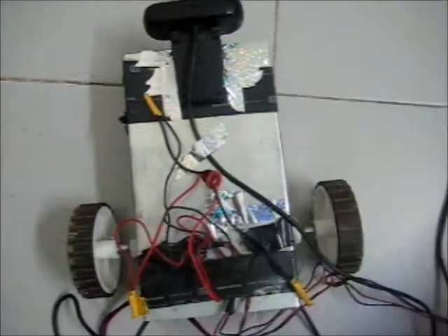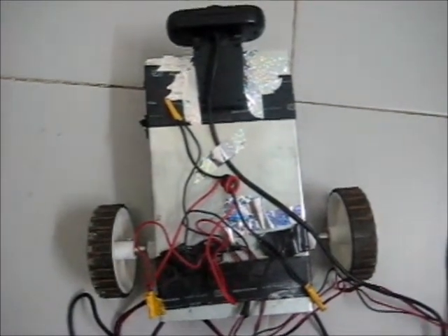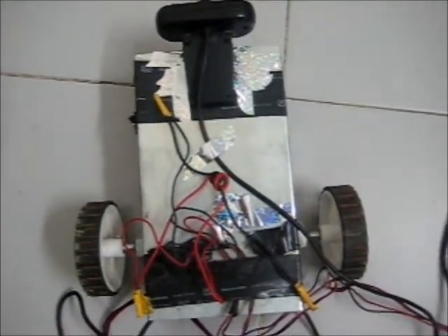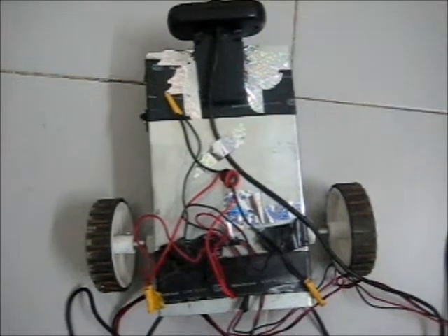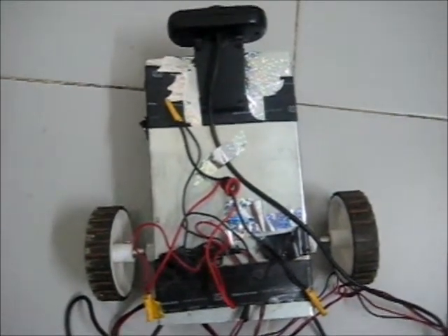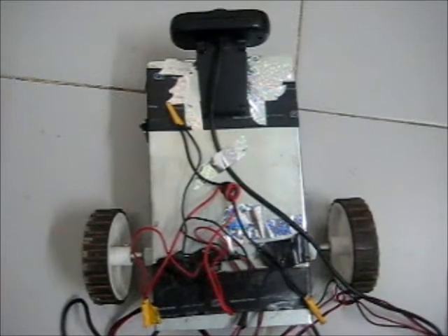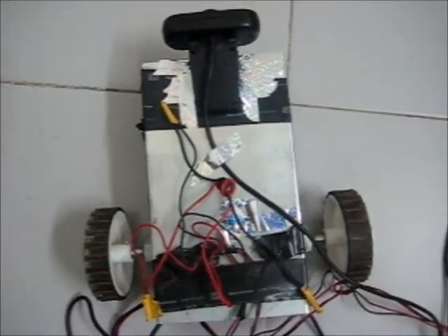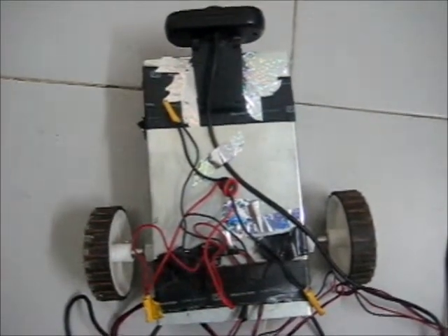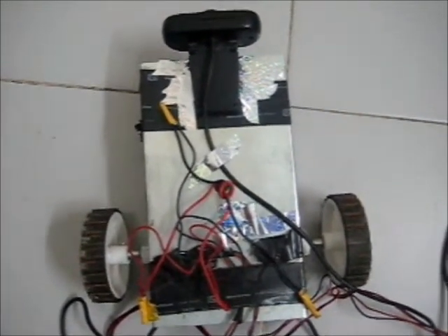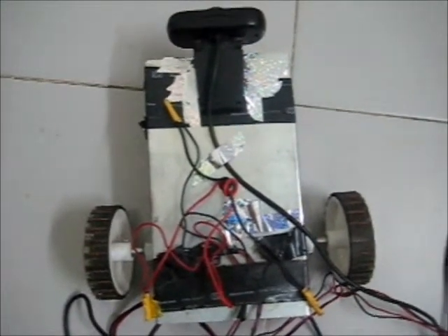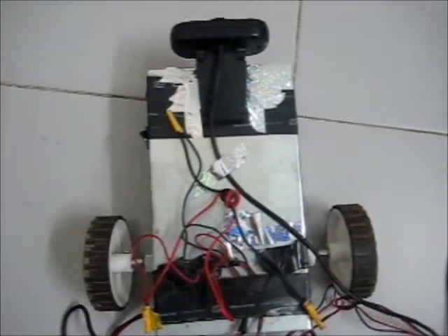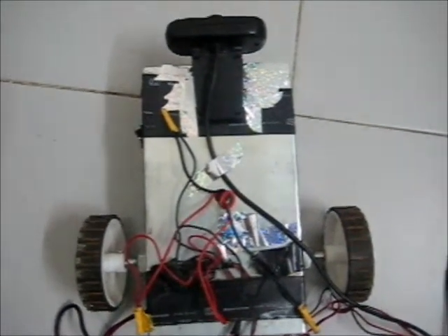We are using a Logitech C100 webcam, which is a very inexpensive webcam. It is a UVC or plug-and-play type webcam with no special drivers that have to be installed except the UVC driver. The webcam is installed on the board and it is the eye to the entire system. It is attached to the BeagleBoard via USB, which continuously renders color frames to the BeagleBoard for image processing. The frame size rendered is 640 by 480. We have experimented on several other webcams such as Logitech C200, Sony and Zebronics.